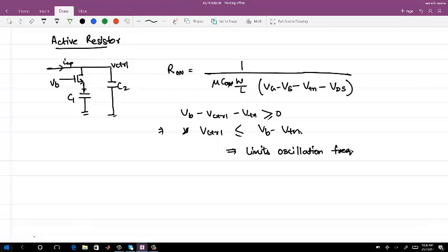For a 0.7 voltage in 65 nanometer technology, it will be hard to have an oscillator oscillating at more than, I would say, maybe 2 to 3, it cannot exceed 5 gigahertz, with regular low VT devices. So you are limiting that voltage. Now I can always have this voltage converted to some other level, with gain, and I think that can be done. Right now this is talking about limiting the control voltage of the oscillator and limiting the oscillation frequency.